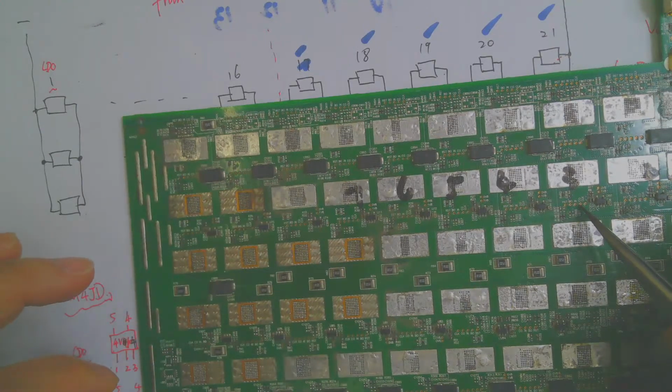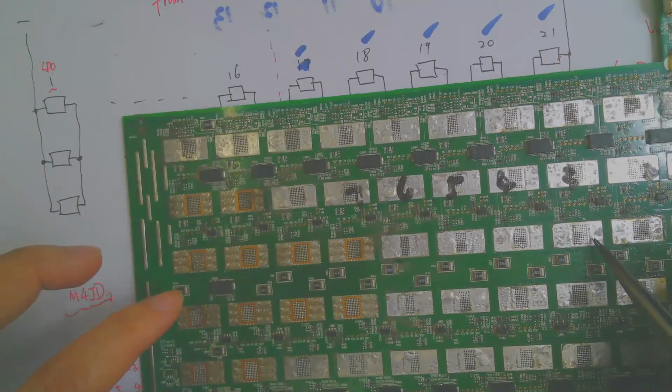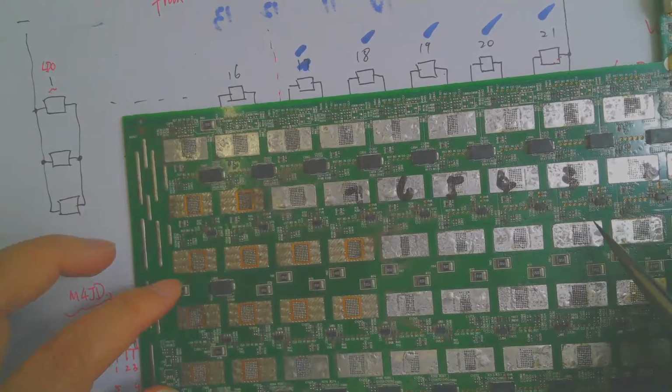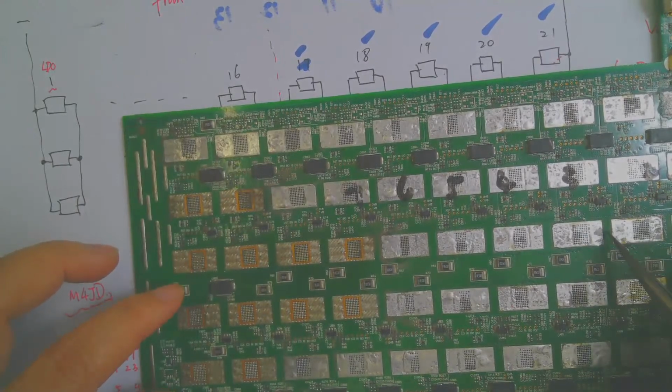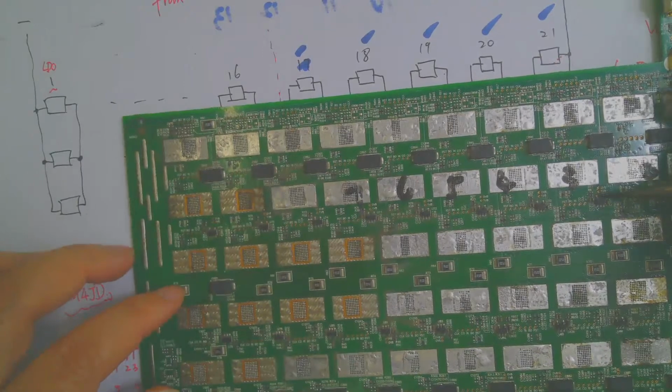If the output is abnormal, then we will try to test the domain voltages and the output of the LDO, to check whether we can measure 1.8 at pin 5, and also test between the resistors to see whether there is 0.8 volt.